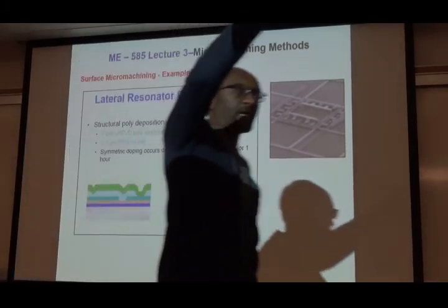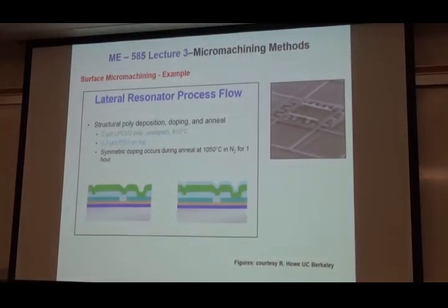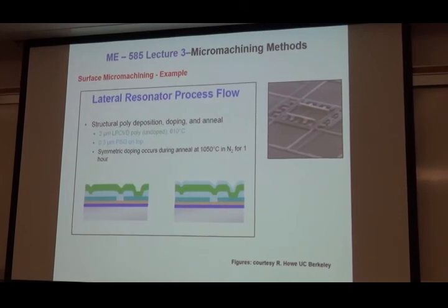Okay, I thought I saw somebody asking a question. Yes? So why would it have a dimple and not straight? Here? Yeah. So I have an experiment for you. When you go home, go to the grocery, buy a gel, and try to deposit it with some container with a hole. The way any viscous material flows, it's going to flow like this. So it's going to fill it up. As you deposit it, remember, the deposition rate is the same. So something comes in, first it has to fill in this guy. As you keep on increasing, this guy has to catch up.